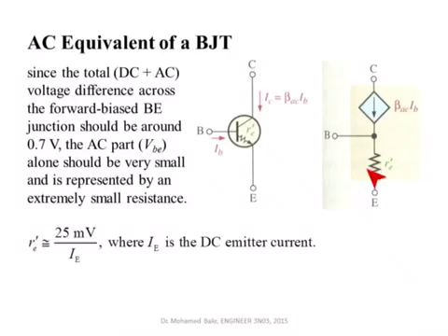The resistance was not there, connecting the base and the emitter. This one was not there. We had really an open circuit between the gate and the source. Okay, so over there we had gm. Here we have beta AC. Beta AC will be given from the data sheet.